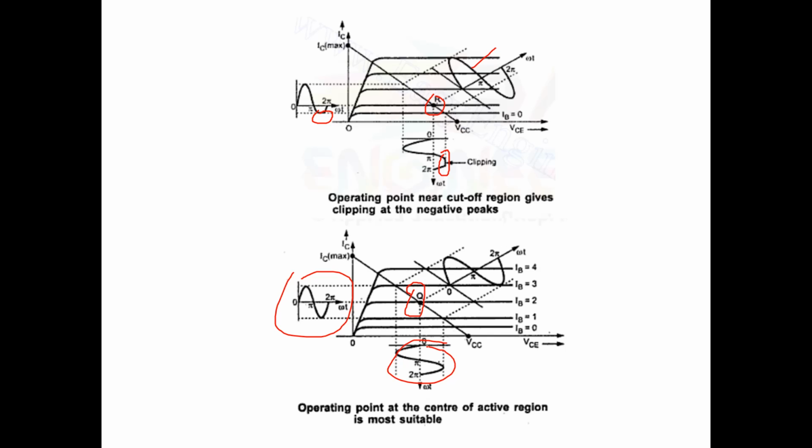How do you select the intersecting points P, Q, R? These are the points due to the intersection of the base current with the DC load line. You are the one fixing that base current, according to the voltage you apply at the base to emitter terminal.